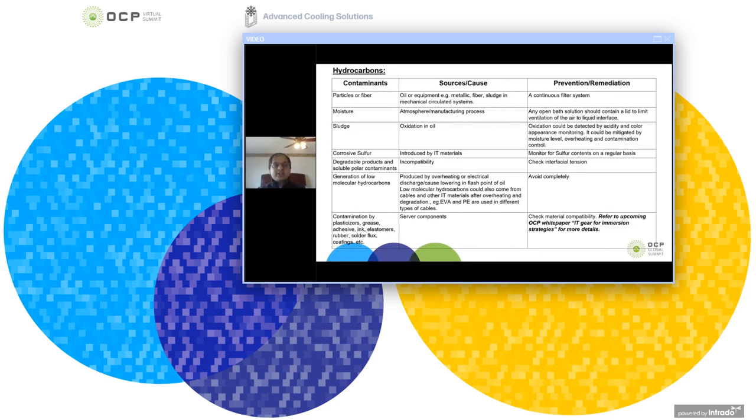So as you can see in hydrocarbons, if you have particles or fibers or human hair kind of contaminants, you can use the in situ filtration system and take care of that. There are some hydrocarbon oils where moisture has an effect on the chemical stability of the oil. That should be taken care of during the manufacturing process, and when you have an authentic, ethical, trustworthy supplier which can provide you all the information, or you can ask them.